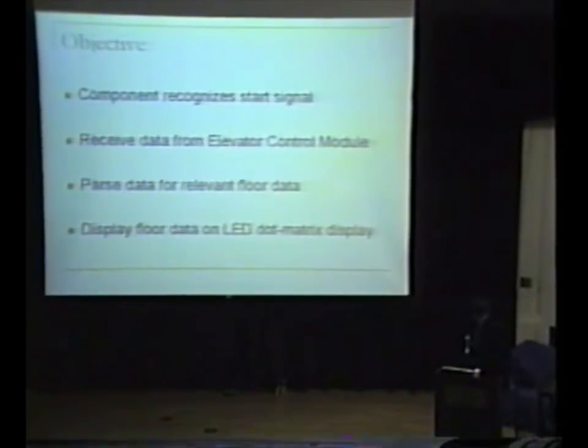First, my objectives. I needed to build a display component. The component needed to recognize a start signal given by the elevator control module. Once this start signal was received, the component would then begin to receive serial data from the control module. This data would then be parsed to reveal the floor data, and then this data would be sent to an LED dot matrix display.